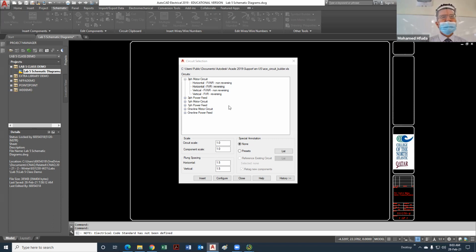You said the resistance. Yes, star delta, Y delta, or auto transformer. Very good. That's good. Mr. Burhan is still looking at me like, you took motors or not? So very important, reduced voltage starting.